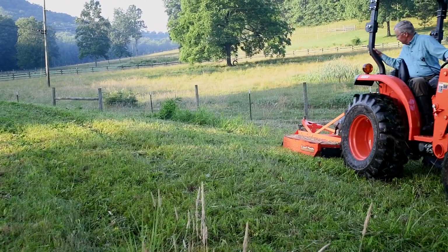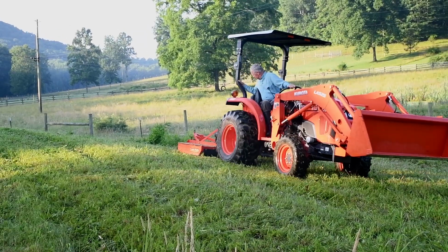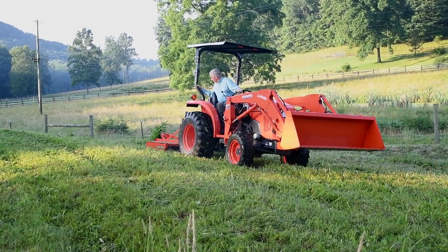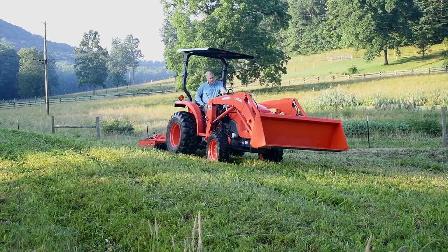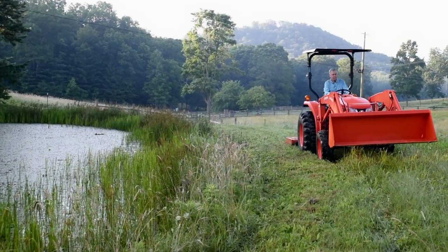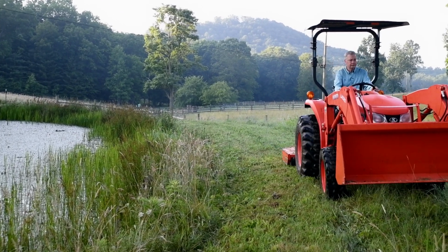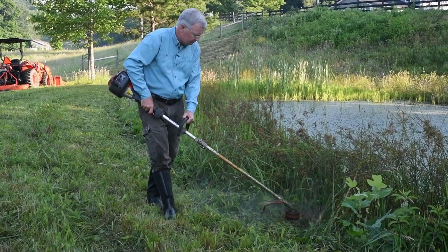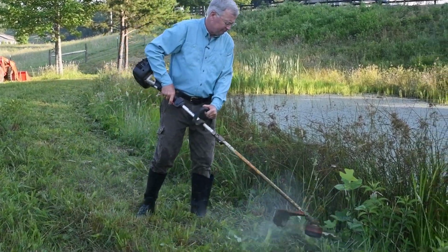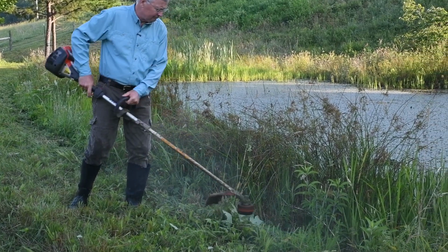Because I don't have a batwing mower, I need to back up to mow the trees and the shrubs that are growing on steep slopes, along the water's edge, and in the spillway. It's important to mow the dam and the spillway twice a year to control trees and shrubs that are growing on the dam. It's important to use a string trimmer to cut trees and shrubs that are growing on the dam and in the spillway that you can't mow with the tractor.